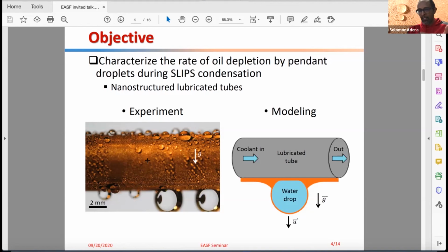If you create some cracks and roughness on the surface, the lubricant just infiltrates into those features and inhibits the solid-solid contact. So from that standpoint, it's advantageous. The good thing about all these slip systems is that they're self-regulating. Whenever you have new cracks and new scratches, the lubricant infiltrates those areas and fills those voids.